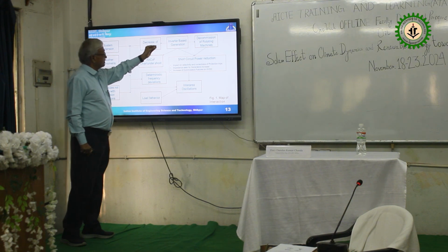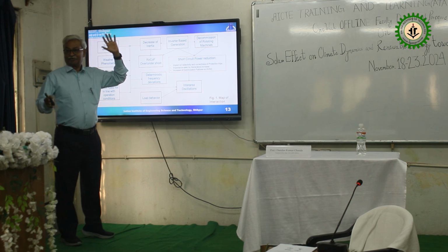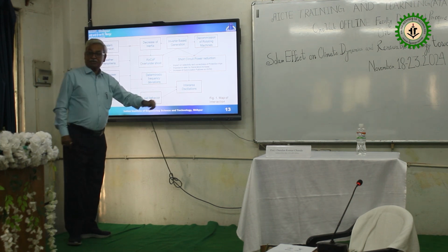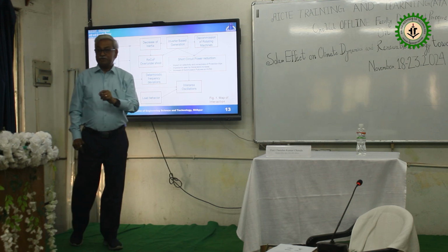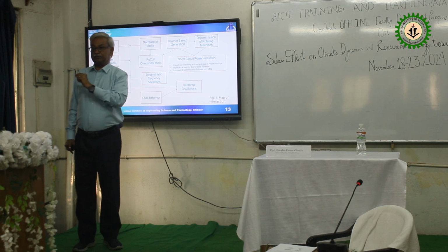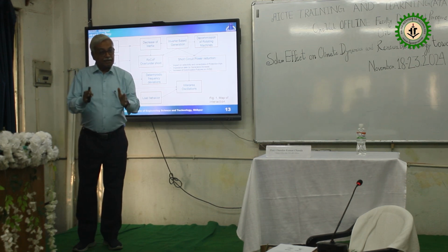And inverter-based generation means by default you are decreasing inertia. By default, no inertia. Once you decrease the inertia, ROCOF will start to come. ROCOF is a very important terminology nowadays. ROCOF means rate of change of frequency. In a normal power station, a turbine is available, no?